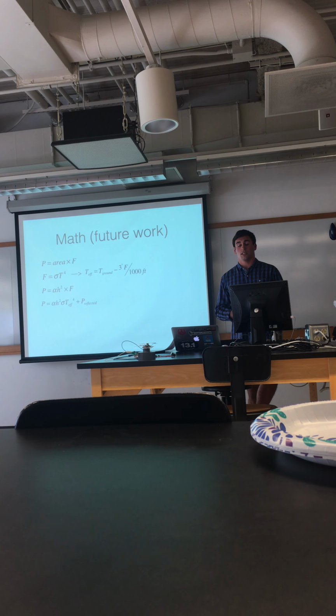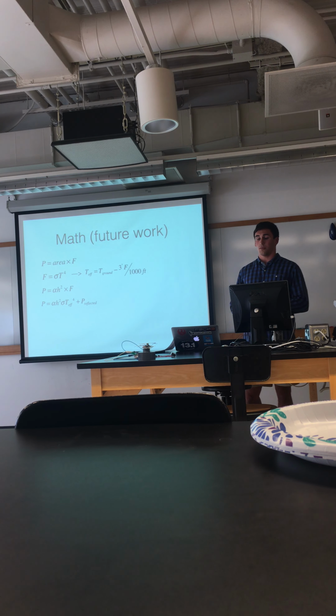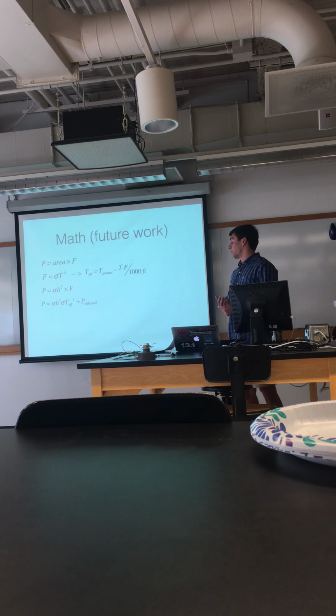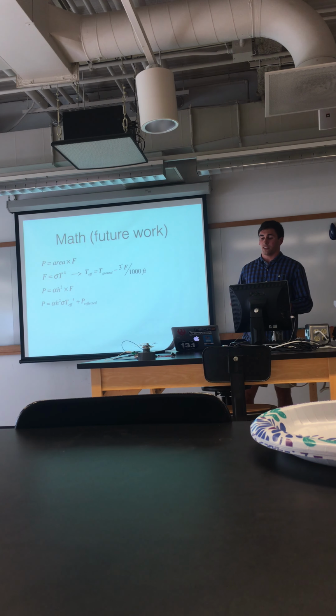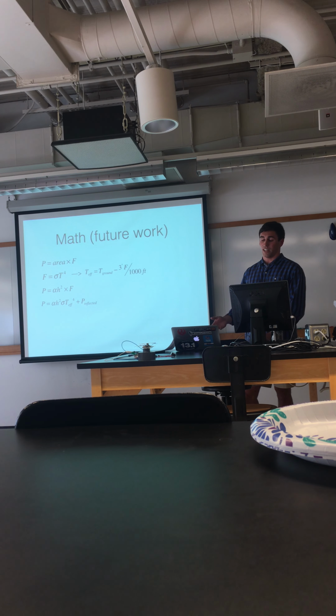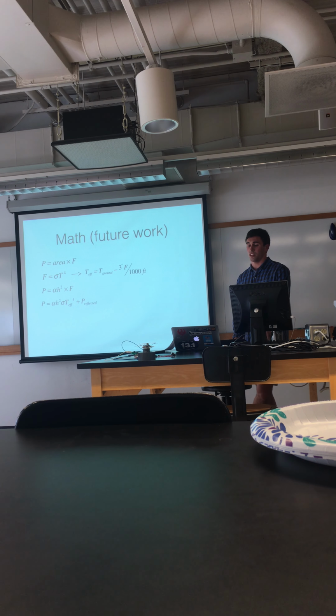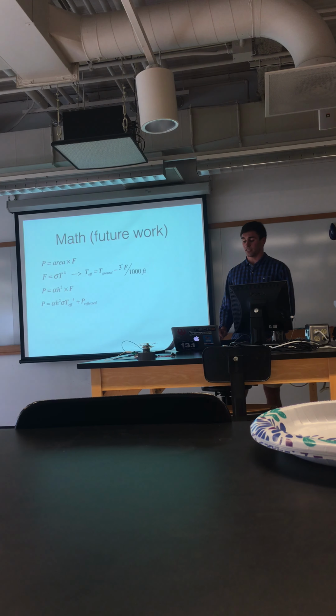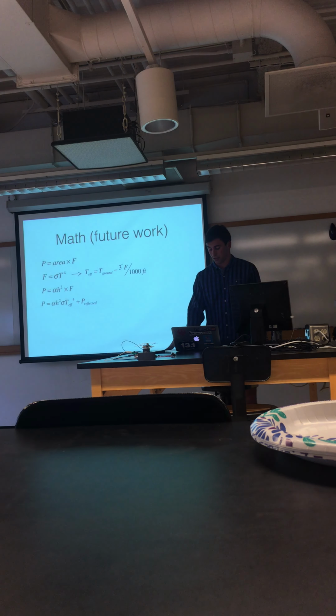And then as soon as I thought I'd get it working, soldering came off from where it was connected to the bottom of one of the components. The problem is you don't know which soldering it is, so you've got to go through, test the voltage, test the signal of each component, and then once you finally figure it out, resolder that component. And so just because of those different roadblocks that I hit along the way, I wasn't able to gather enough data to come up with that baseline to calibrate the device, and then be able to do this work.